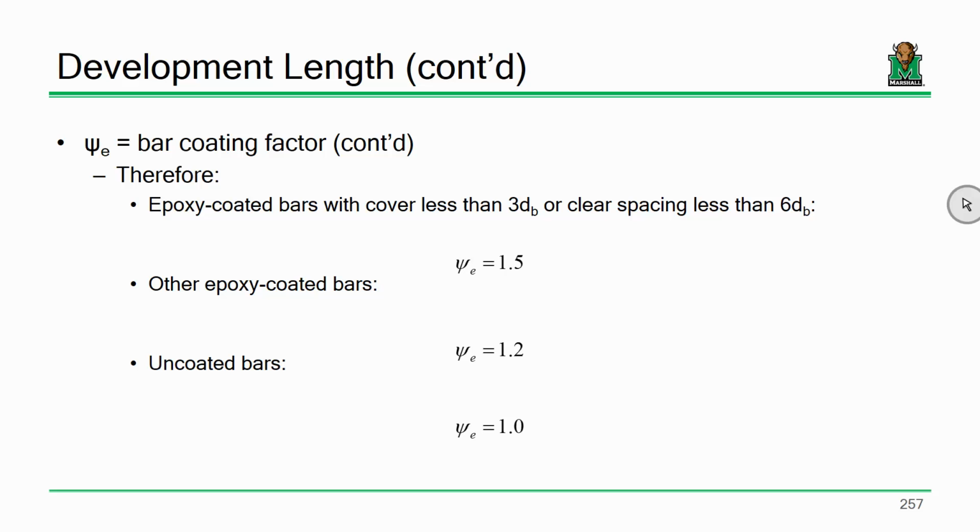You're talking about galvanization. You're exactly right. Galvanization is a potential coating solution that doesn't involve epoxy coating it, and you get sort of that same grip. Galvanization of bars can be a little more expensive. So again, it's a trade-off. It just depends on the scenario that you're looking at. But you're exactly right. If you dipped bars and didn't epoxy coat them, you could get the same benefit without having to use a larger psi value.